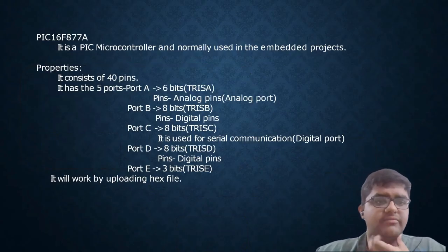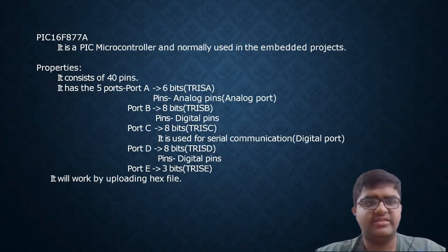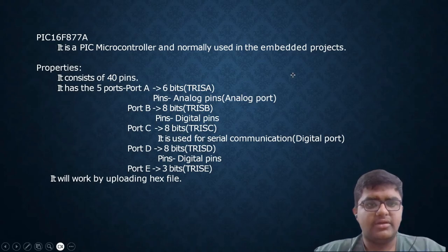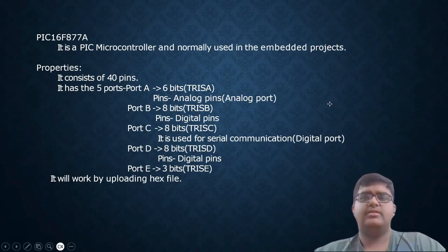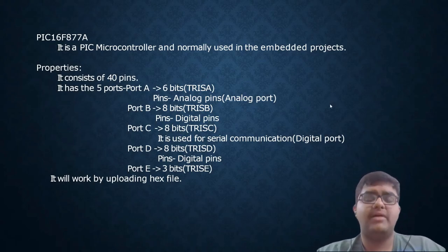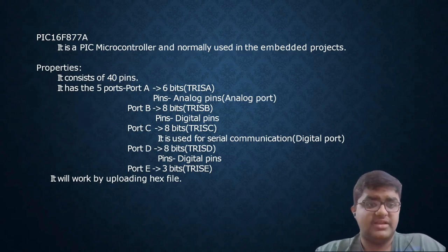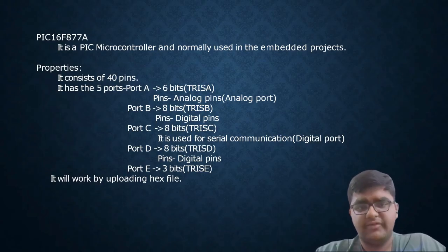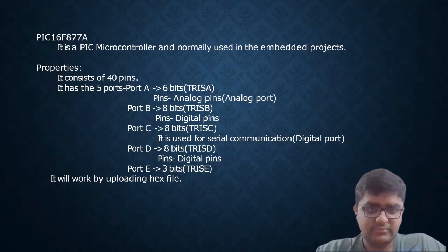So, something about the PIC16F877A. It's a PIC microcontroller and normally used in embedded projects. It's developed by Microchip. Properties: it has 40 pins, it has 5 ports. Port A is 6 bits, port B 8 bits, port C 8 bits, port D 8 bits, and port E 3 bits, defined by TRISA, TRISB, TRISC, TRISD, and TRISE.